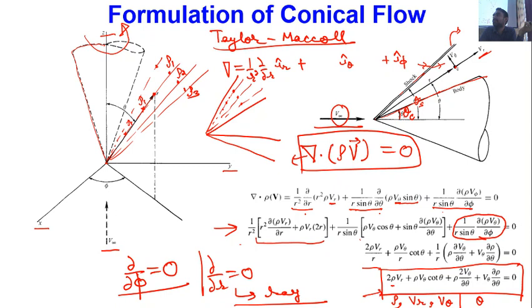Okay, what will be the change in its entropy? That will be the same everywhere, whether you check here, here, or here. So for any streamline, whether you take it at this end or at this end, behind the shock wave, the entropy of that particular flow field will be the same everywhere. If the entropy of the flow field is the same, it means the gradient of entropy is equal to 0 for this situation.